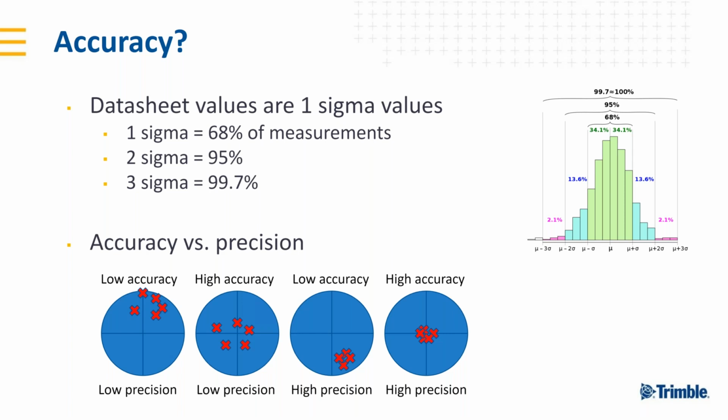Then another thing, which for surveyors I think you should be very familiar with: we have something called accuracy and something called precision. Accuracy you could say is a description of systematic errors. So it's the difference between the result you get and the true value, what it should be. And precision is more of a description of random errors in the measurement. So the deviation, if you do the same measurement over and over again, how much the deviation between these measurements